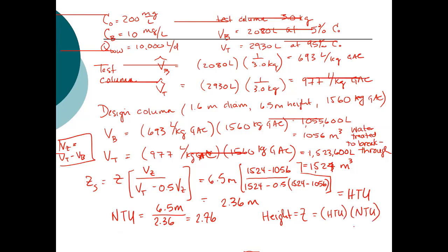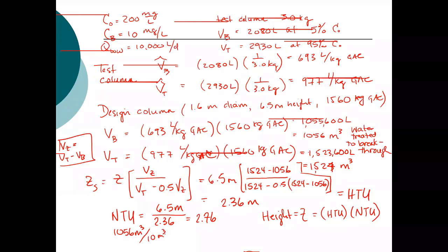And the time to breakthrough, we can treat 1,056 cubic meters. We divide that by the flow rate, which is 10 cubic meters per day.